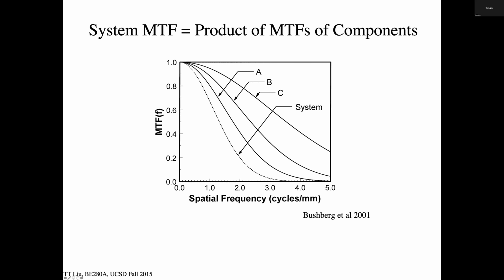And they'll say, our modulation transfer function is much higher at these higher frequencies than everybody else, right? Sometimes they'll just give you one value on this function. They'll give you a value of the spatial frequency at which this gets down to a certain level. And depending on the manufacturer, they'll decide what that important level is, whether it's 10% of the maximum or whatever. So you need to read those actual numbers carefully, because they'll say, oh, we have a cutoff of like 19 cycles per millimeter. And you're like, oh yeah, but you're down to 0.1% or something at that point. But anyway, that's how systems are often characterized, right?